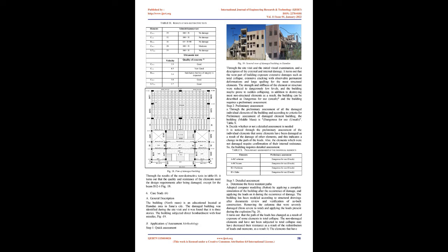As a result: 1. The elements that have been exposed to damage severity, severe to total, should be removed and rebuilt using appropriate scientific methods. 2. The elements that have been exposed to damage severity, moderate to heavy, can be restored using appropriate scientific methods but after assessment of residual strength. 3. The elements that have been exposed to damage severity, slight, can be restored using simple ways but after assessment of residual strength. 4. The elements that have been exposed to damage severity, none, should be assessed for residual strength.